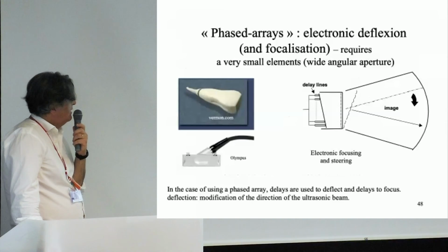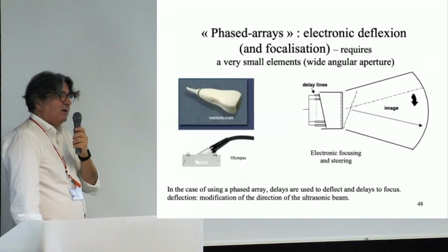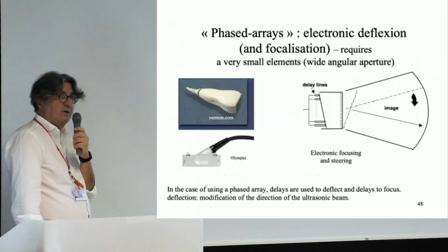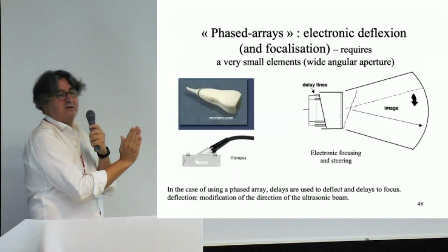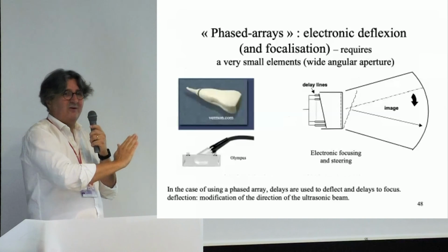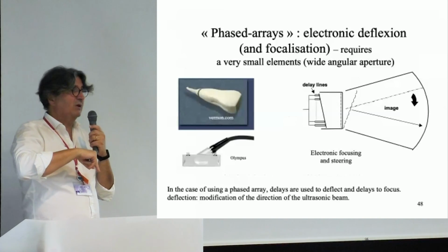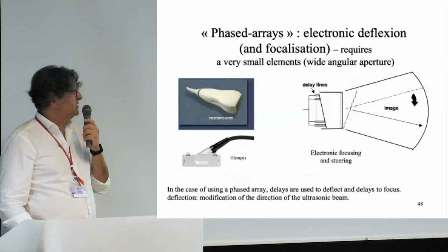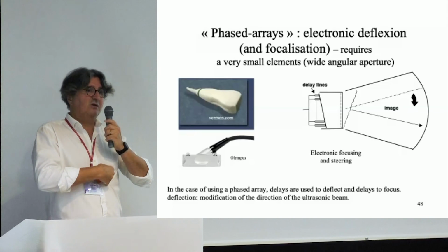So here you have an example of phased array. You are doing not only focusing, but you can manage deflections. This is very useful in metals because you put your probes and then you can just look on the side to generate and to inspect a weld, for instance. And for medical imaging, it is important for heart imaging because of the thoracic cage.